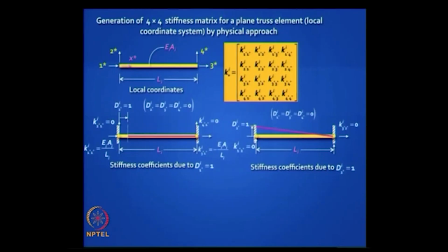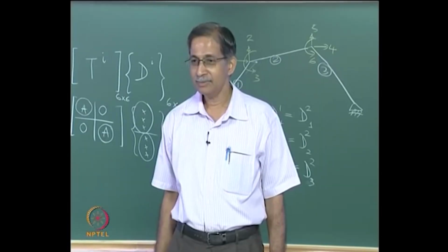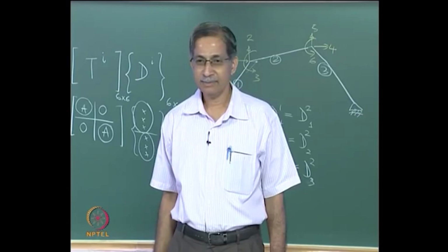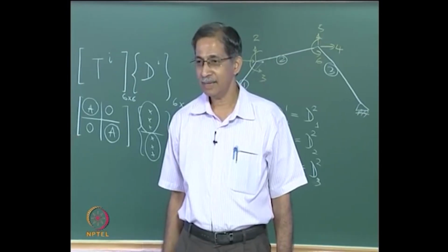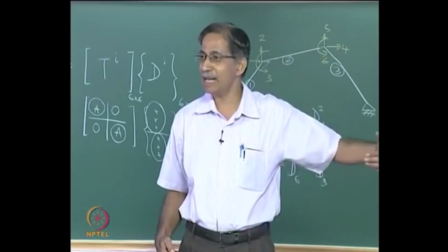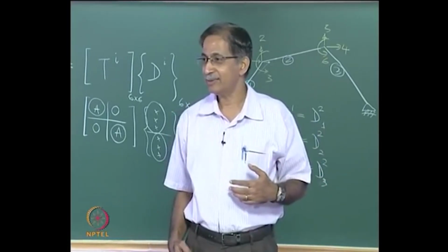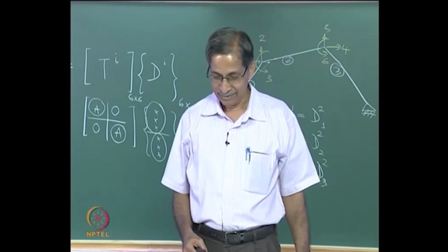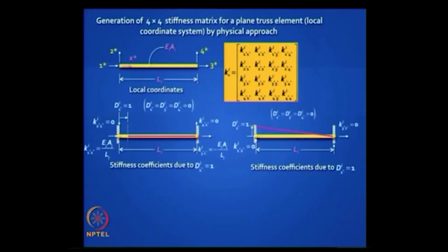You see, all you have to do is to lift it up. Yes, sir. Like a rigid body. But why not displace it? That member has stiffness only along its own axis. So he gave the correct answer. All you do is to lift it up. It will move like a rigid body because you are allowing that movement and it's pin jointed.